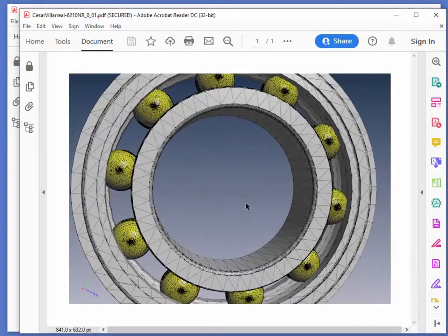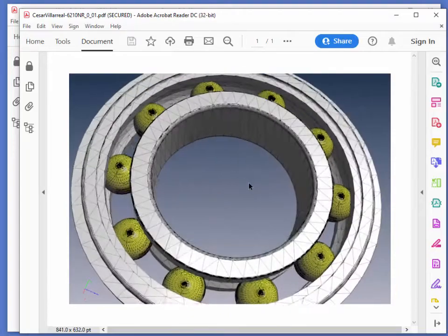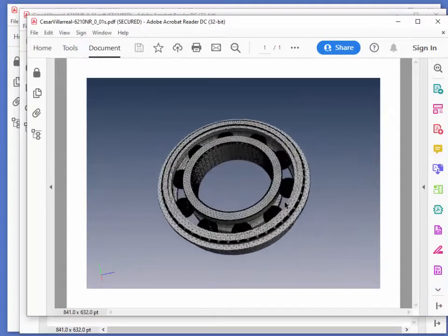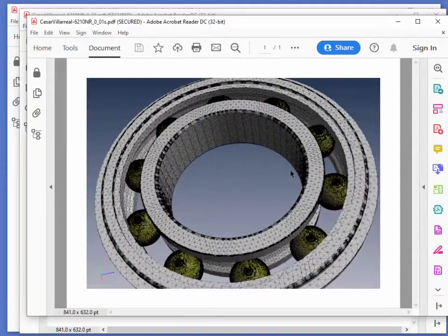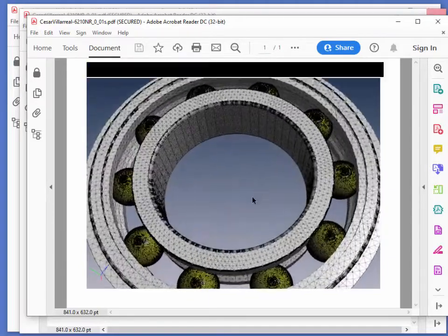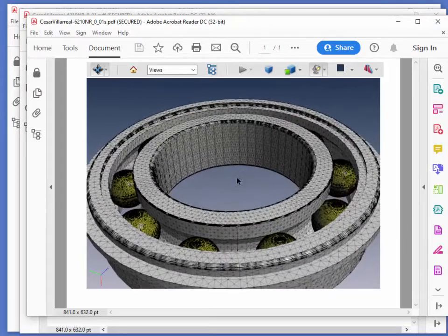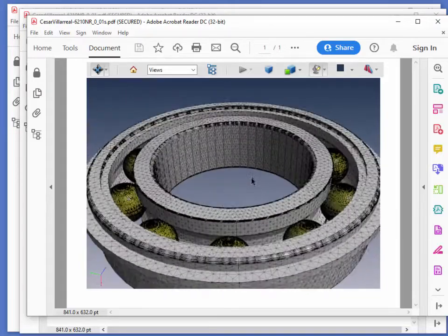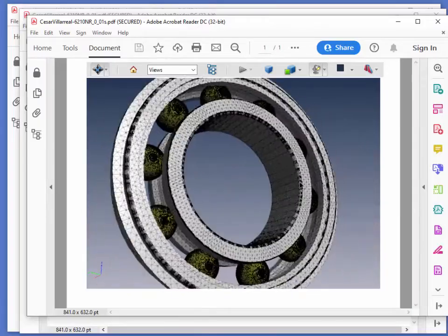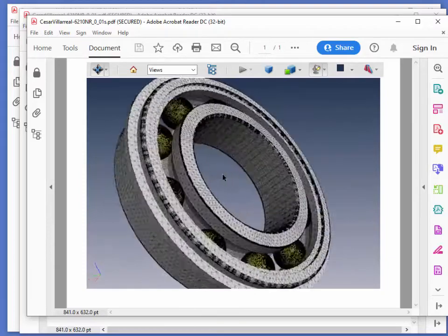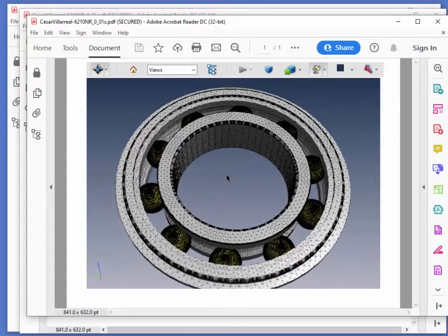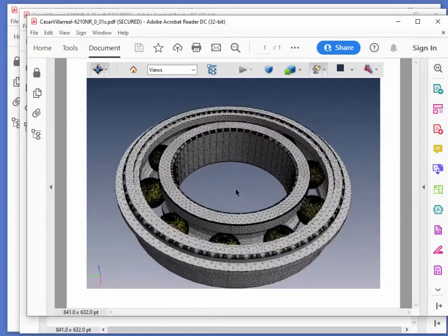However, we can see that the flat areas still have coarse tessellation compared to the ball bearings. A new feature added in this release is to allow for further subdivision, where both the curved surfaces and flatter surfaces can have a more uniform tessellation density, not completely related to curvature. This allows for a more uniform mesh, which can then be further processed in things that require a higher quality subdivision. The curvature of breps and the subdivision for planar surfaces are independent parameters and can be controlled according to the model conversions that you're needing to perform.